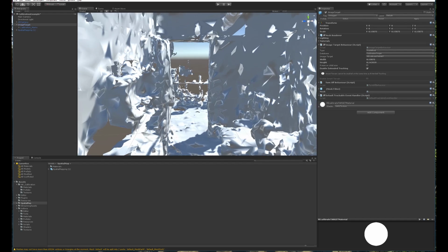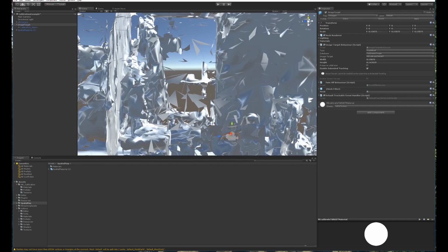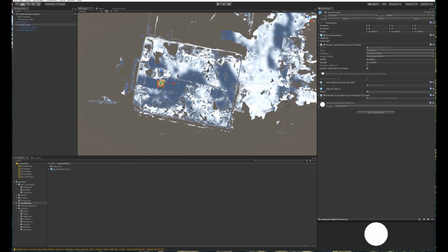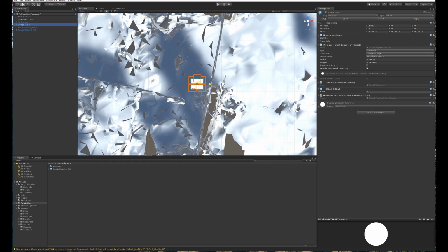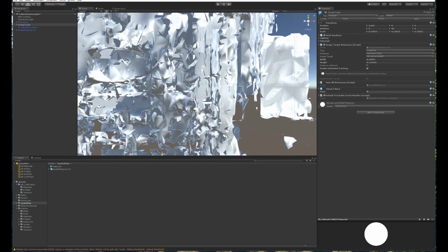So again, going back to isometric view, looking from the top down, let's just start doing this right. I'm going to move it over and zoom into it. Now I know that my doorway is here on the right side, so I need to rotate this whole thing. I think it's rotating on the y-axis, correct? And I need to rotate it this way. So I'm going to do a 90, just type that in. Okay, so now if I look at it from the side view, I need to rotate this up, so that's on the x-axis.